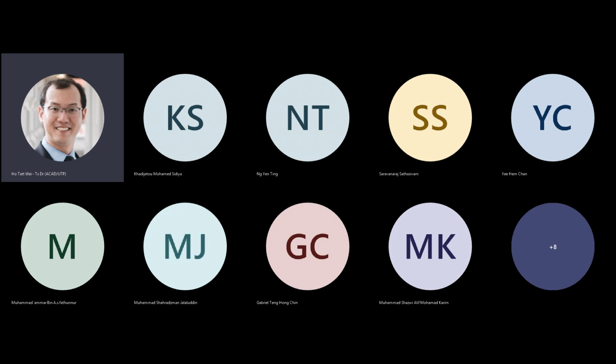So although we build sequential circuits, like Mealy machines, as I've tried to explain, and if you don't understand this, let me know. We really have to make sure that you understand this clearly. A sequential machine is nothing else but combinational logic that you design interspersed between D flip-flops. That's a sequential machine. So really, we're back to studying just the critical path in all the small groups of combinational logic in the circuit. We pick the critical path and we evaluate it. We estimate the delay for that. That sets the fastest speed at which the circuit can operate.